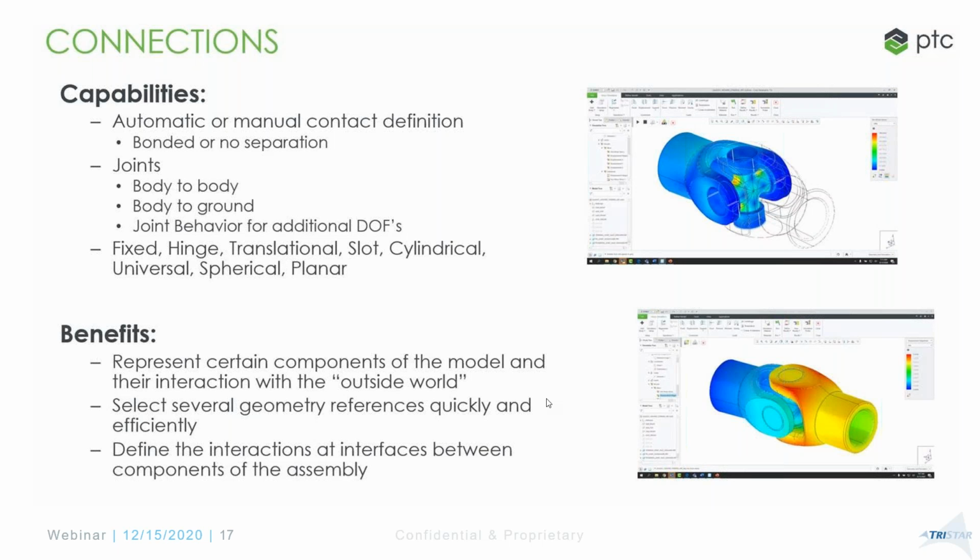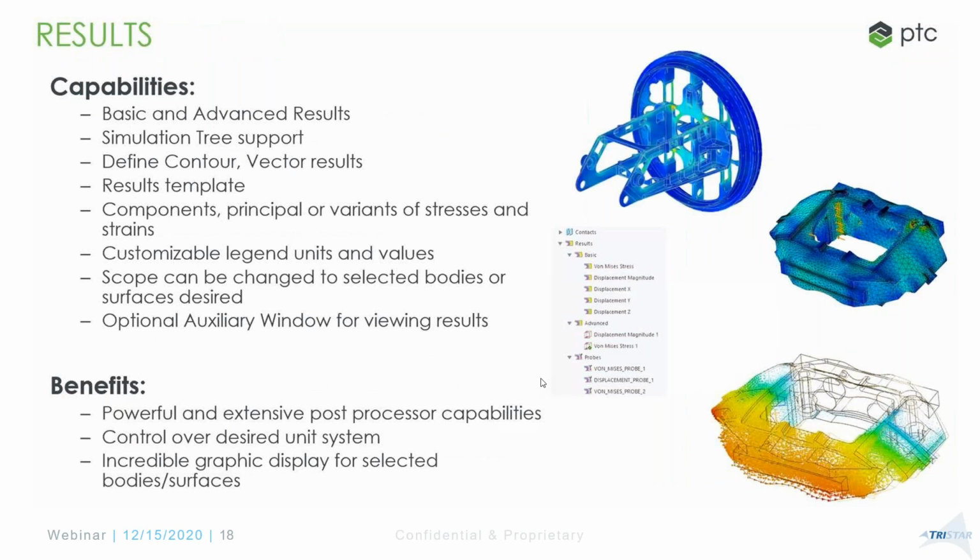We are able to control that joint behavior, right? And then finally, results. As always, results are important both for reporting purposes as well as for you to interrogate the model and see in an assembly, look at the stress plot, deflection plot, look at specific geometry of interest with the mesh, without the mesh, look at the animation. Is it kind of deflecting the way I would have expected in the real world, right?